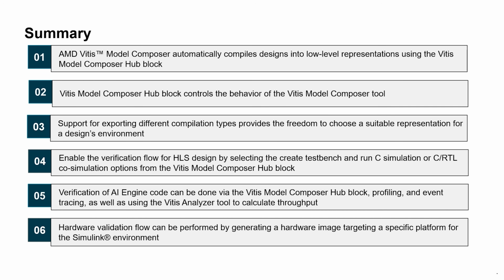Verification of AI engine code can be done via the Vitis Model Composer hub block, profiling, and event tracing, as well as using the Vitis Analyzer tool to calculate throughput. And finally, hardware validation flow can be performed by generating a hardware image targeting a specific platform for the Simulink environment.